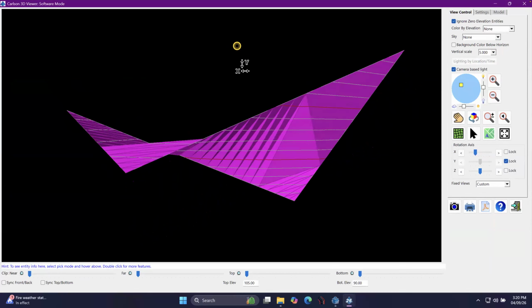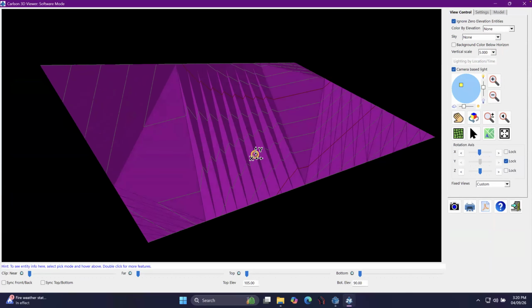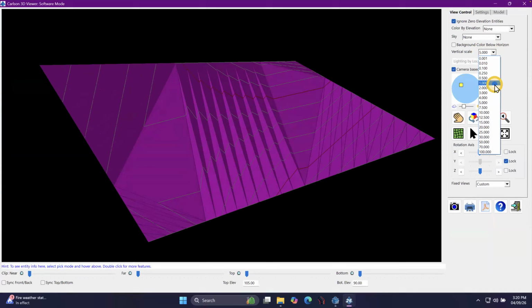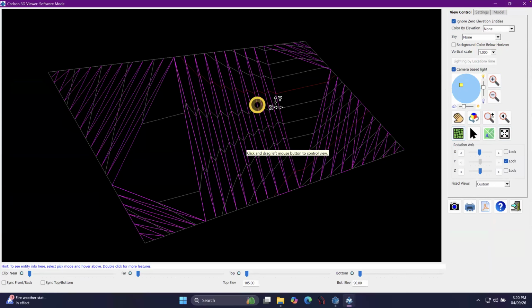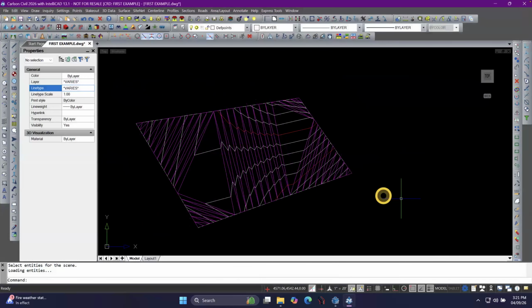And when you get something that looks like that, with these contours doing all this, there's a way to fix that. A lot of people will reverse the triangle direction and try to edit the triangles, but that's not the right way. The right way is to figure out what caused that. Maybe if I put lines across here, that would help define the interior space a little better. I'll show you how that works real quick.